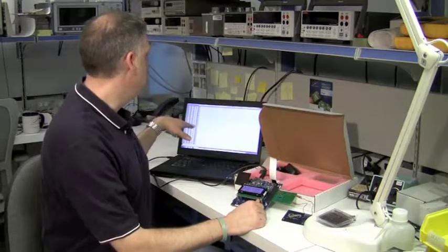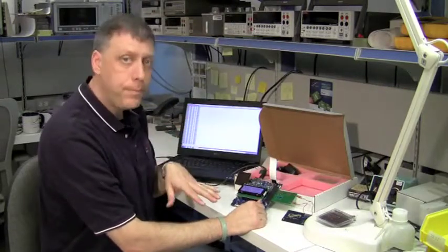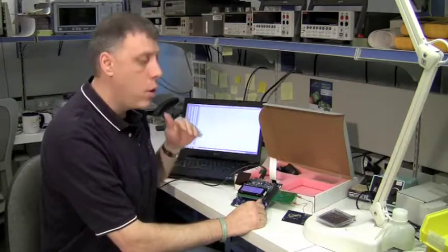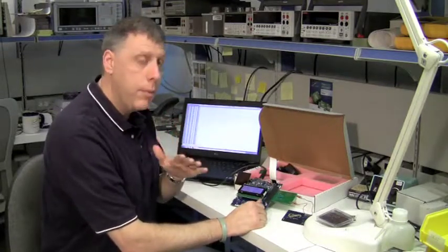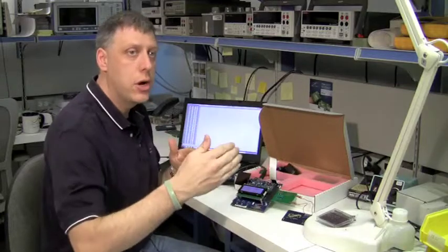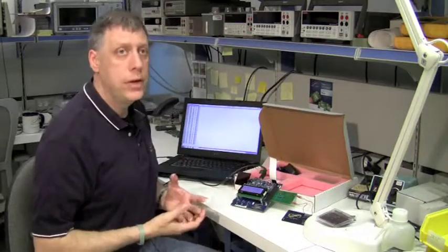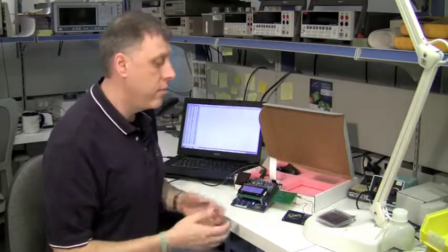And the way I'll know is that if my voltage keeps going down, in other words, it doesn't hit a stabilization or balance point, or if my voltage goes up, meaning that it's continuing to recharge over time, then I've got an energy balance that is in excess of what I need. If I don't have either one of those two conditions, in other words, the voltage keeps dropping till the MEC becomes fully discharged, that means that I'm not getting enough energy from my energy harvester or from my environment.